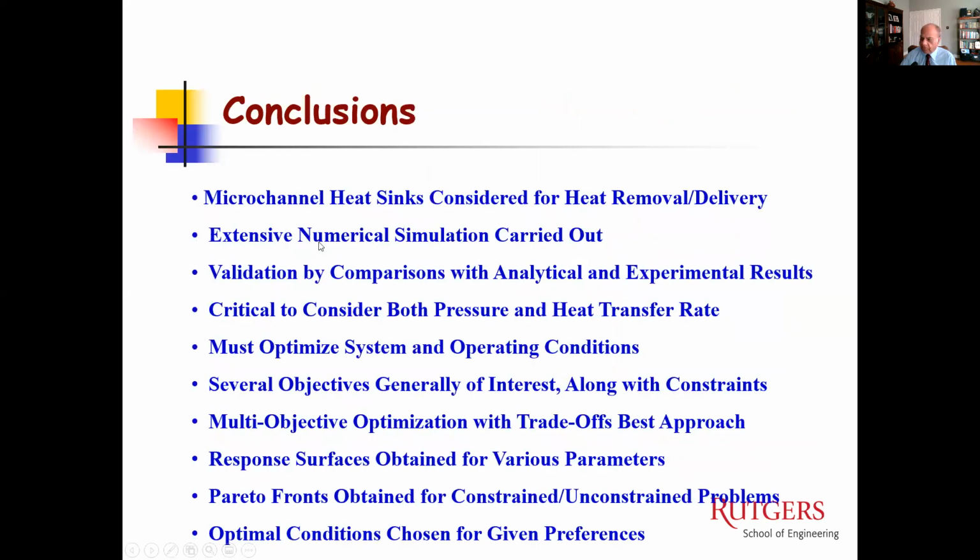Let me conclude because I'm running out of time. Microchannel heat sinks have been considered for heat removal and delivery. We did extensive numerical simulation. We validated by analysis and experiment, but it is critical to consider both pressure and heat transfer rate. You just cannot leave it with one. Single optimization is not the best answer. You must optimize the system and operating conditions.